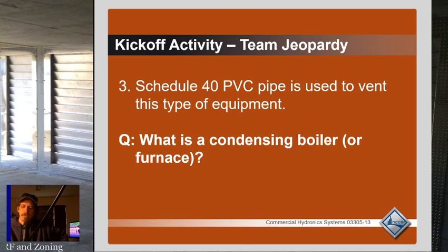That's just my 2 cents. I don't think you'll find that in a manual anywhere or anything like that. That's just based on when I looked at where your temperatures were going to run and what your flue gas temperatures would be at those temperatures, and so on and so forth. That's kind of the rule I came up with. So usually I won't say spend the extra money on that expensive venting unless you're running high temps.